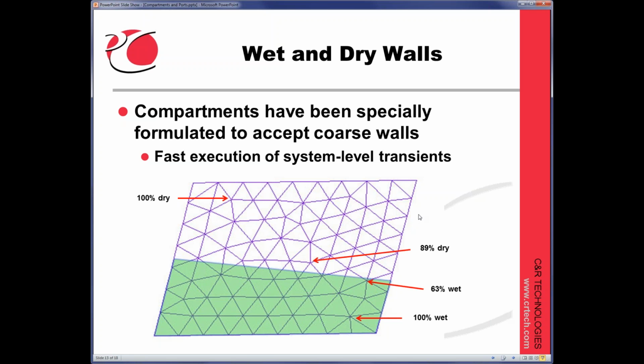And here's an example of one that's above. And you might look at these and say, hey, this is below the surface, shouldn't it be 100% wet? And this is above the surface, shouldn't it be 100% dry? Well, remember, this is finite elements, so it's actually the function of all of the elements of which this node is a member. And in this case, it knows that it's got a fraction of these surfaces.